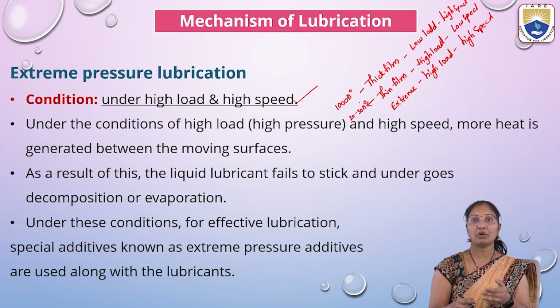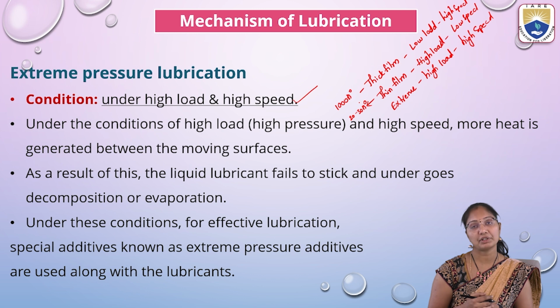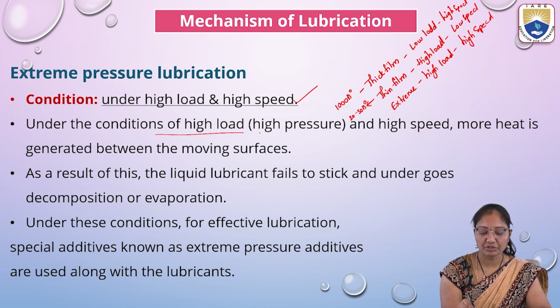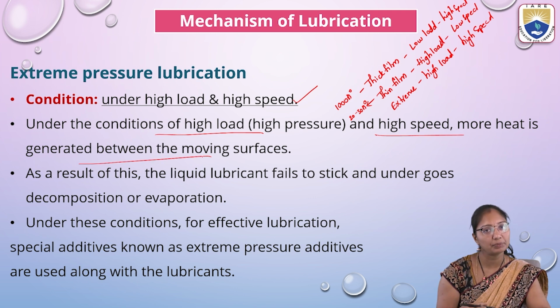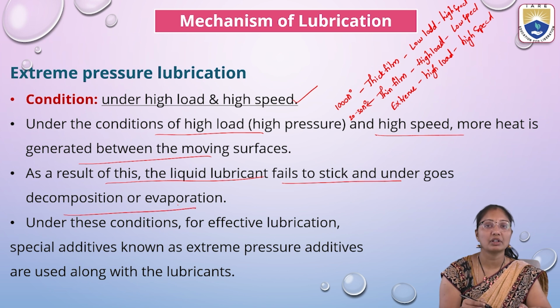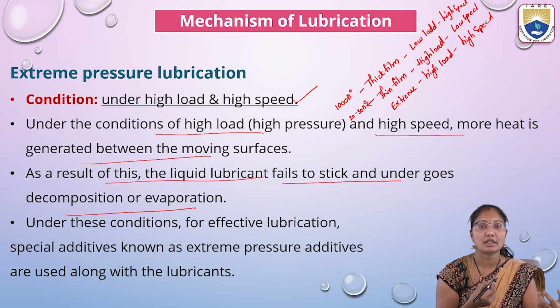Here we will see how it is going to be in extreme pressure lubrication. Under this condition of high load and high speed, more heat is generated between the moving surfaces. Because of high speed as well as high load, there will be very high pressure. So the name itself is extreme pressure lubrication. As a result of this, the liquid lubricants being used fail to stick and may break down or undergo decomposition, or evaporation can also happen because of the high speed and even with the